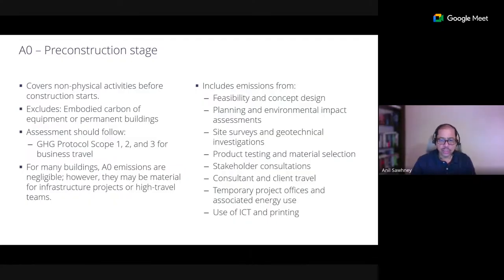Obviously, the way I'm describing it to you, for a simple building, A0 is negligible. So generally, as a rule of thumb, in the WLCA standard, we do not report A0 pre-construction acquisition stage emissions for buildings. Imagine for a large infrastructure project, it's going to be significant.